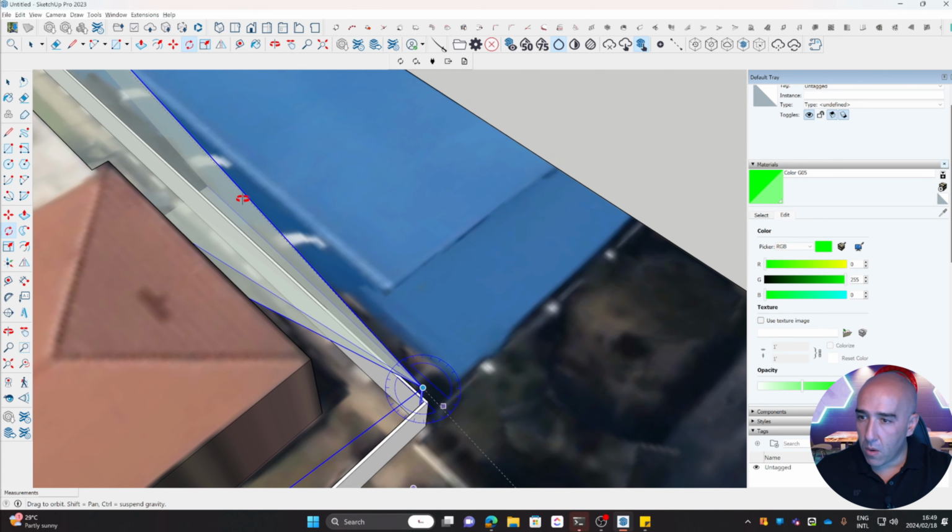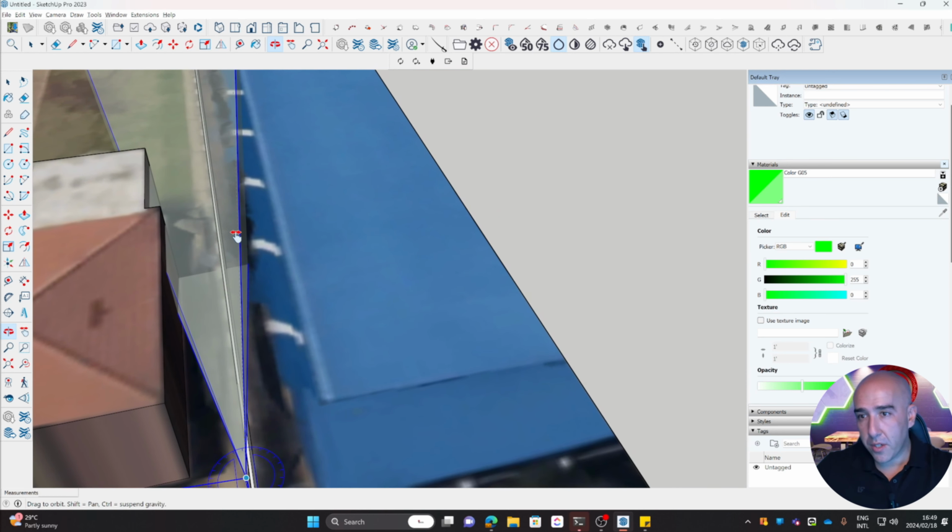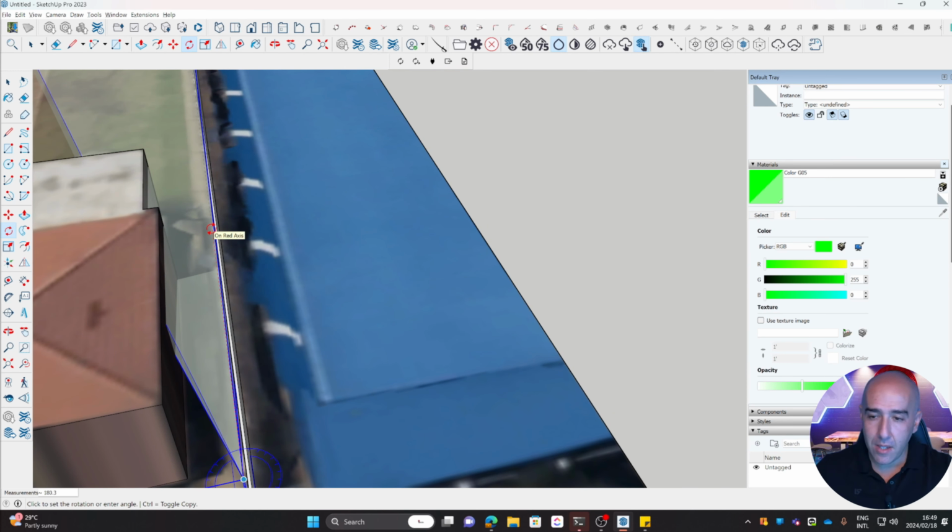Okay, now in this situation we have a neighbor. Unless the neighbor says it's okay to hang your camera onto his side of the property, then we'll have to have an angled pole so we can see on the other side of the wall. So when it comes to perimeter protection, we should be looking on the outside to detect them. We don't want them already inside. But you're going to have situations like this where we don't have a choice.